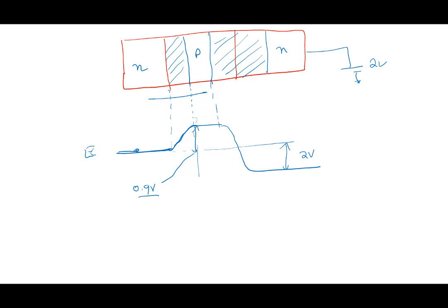But suppose, instead of 2 volt here, I apply 5 volt here. If I apply 5 volt, the depletion region comes till here. The two touch each other. Let's say this is 5 volt, or let's call this the punch through voltage, VPT. I apply a voltage large enough so that there is no neutral base width, nothing is left. The two depletion regions touch.